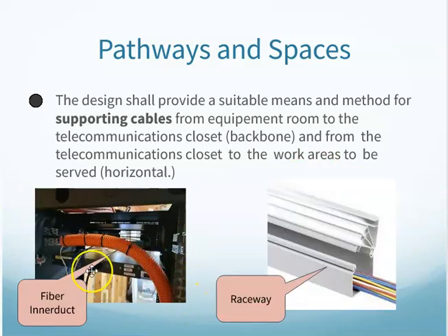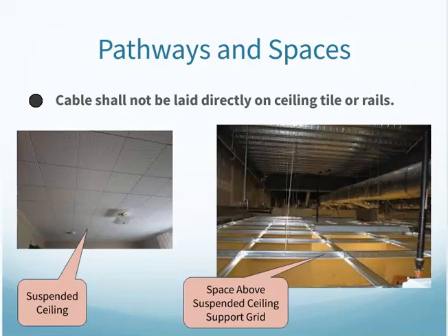We're also talking interduct to support fiber optic cabling. Interduct is a tube. It kind of reminds you of swimming pool hose, if you will. It's a tube that you install that allows you to pull the fiber optic through with low resistance. And after it's pulled in there, it now has a protective tube around it from other cabling or other things that are in the tray. And we're also talking raceway coming down the wall to outlet boxes. They remind us about in the ceiling.